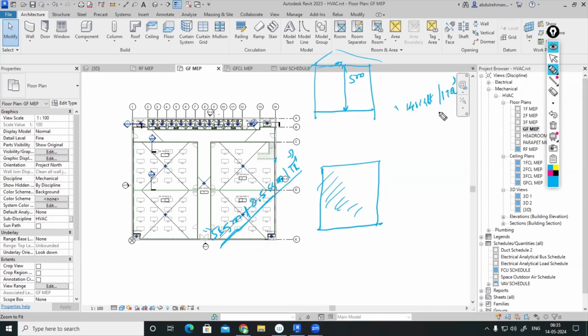Correct. That's why this thumb rule is not for the project. Thumb rule is just to find the floor area of the plant room. But when we are doing the project, you know how we do all these things: how we have to do the heating and cooling load calculation using HAP or the E20 method. Accordingly, only we will select the machine. The same way we did that. But when you are working in a company, after the feasibility study, when we are doing the in-house meetings, we have to give this input to the architect. They will ask the rough dimension of the plant room. Okay, rough dimension of the plant room, then how to arrive at it.